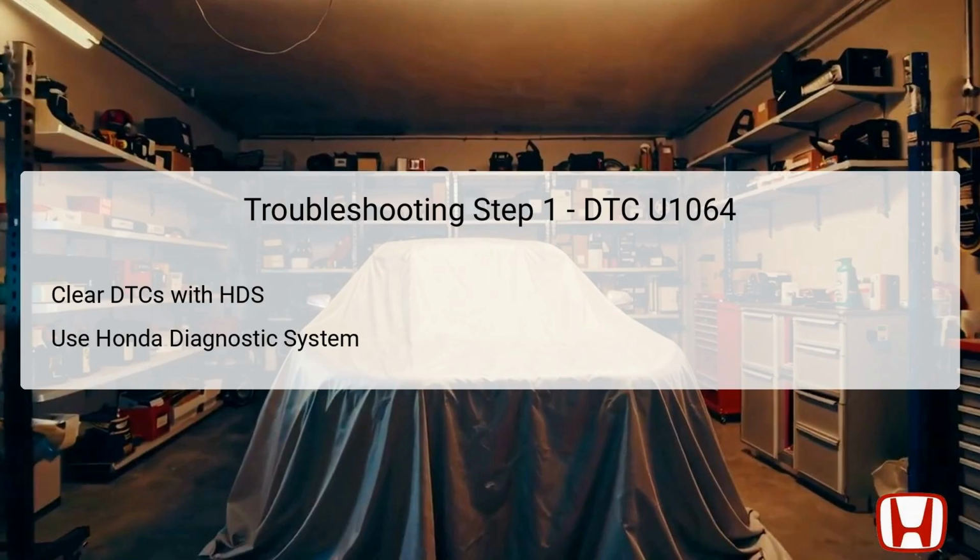After clearing the DTCs, it's essential to follow up by turning the ignition switch to the lock position, then back to the on position. This action resets the vehicle's electrical systems and allows you to accurately assess new codes that may emerge post-clearance. The HDS is a specialized diagnostic tool crafted specifically for Honda vehicles, ensuring precise measurements and error reporting, which is key in diagnosing issues efficiently.